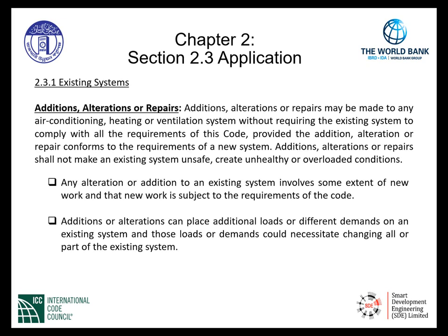If we decided to analyze an existing air distribution system for air conditioning based upon a new building addition, and the engineer found that the existing system has enough capacity to serve the addition, then the new work would have to be compliant with the new code requirements. So we take it from the existing system where we tap off of or extend from, and all of the work from that point to the new addition is required to comply with the current code.